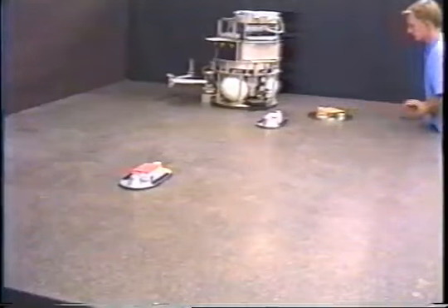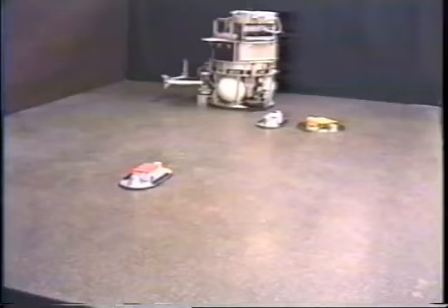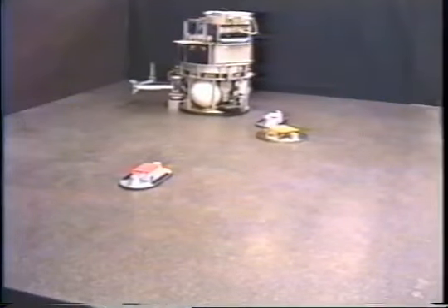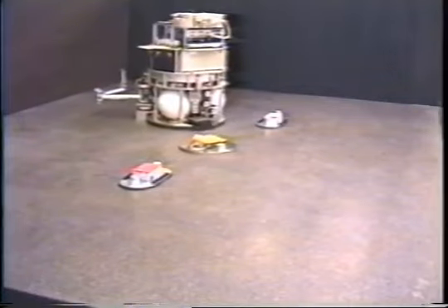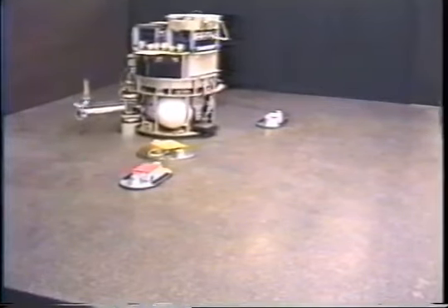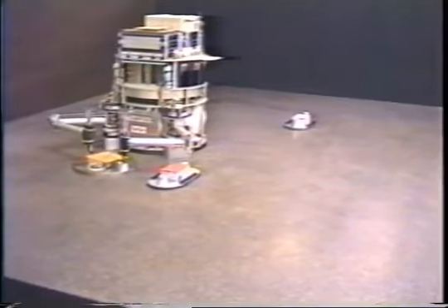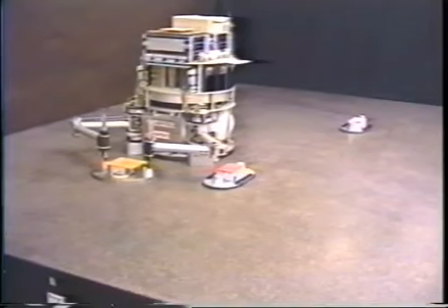The real-time dynamic trajectory optimization system not only produces highly efficient trajectories, it is also able to react to unpredicted events because the constraint equations of the optimization system are modified in real time according to live sensor data. In this demonstration, the robot is able to react efficiently to unpredicted maneuvers made by the target vehicle.